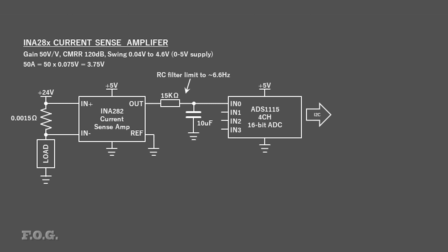Next up, this signal goes into one of the 4 switched inputs of the ADS1115, a 16-bit ADC that I'm using. I purposely sample at a rate of 10 Hz, and this should hopefully be fast enough not to miss anything given the upstream 6 Hz RC filter. And even though this is actually a 16-bit ADC, it samples in the positive and negative directions. So for my application, where I only provide a positive moving signal, it's basically a 15-bit ADC with a maximum range of 32,767.